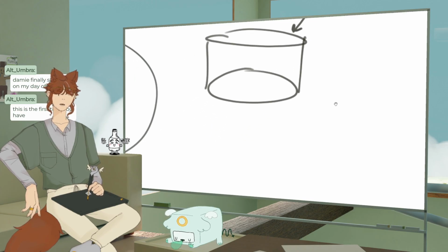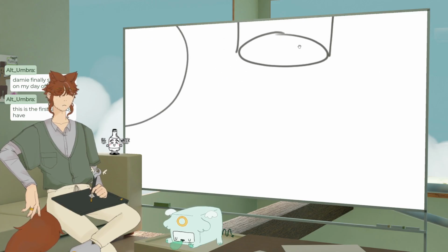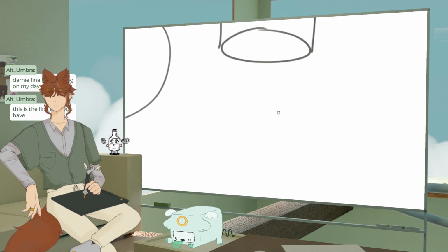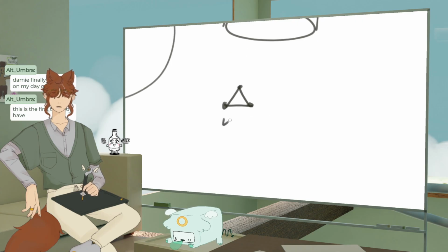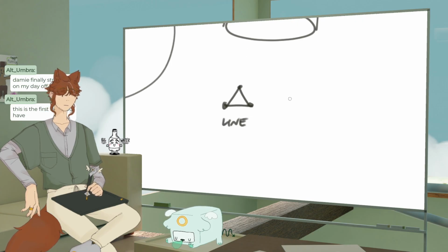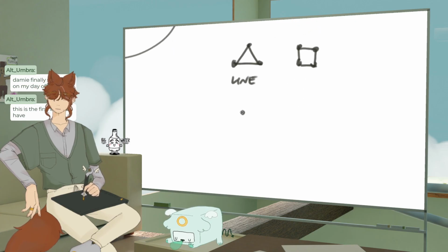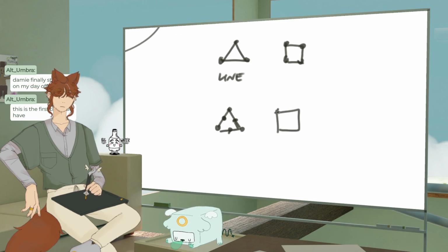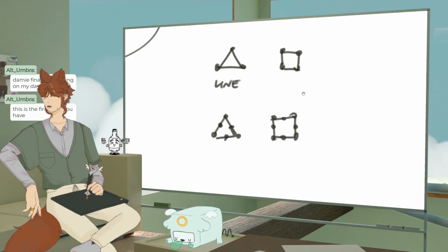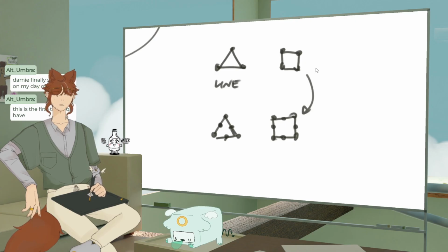But with mesh modeling, it's kind of like the difference between vector versus raster. So we're gonna use other shapes to make up these shapes. And the shapes that we have at our disposal are this, which is called a linear triangle. And then we have a linear quadrilateral. And then we have fancier ones, which is the quadratic triangle. So it has extra vertices here. And the quadratic quadrilateral. So we need to use these, but at the end of the day, it's just like we're either using squares or rectangles.